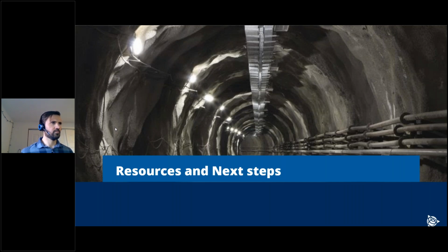Just came in. Oftentimes we lose GNSS connection inside a tunnel. Do inspection scans need to be shot from the exact same location for accurate results? Hey, Dane, thanks for the question. So this is where I think the real power of the SX12 is, because when you scan with the SX12, it will reference to your survey control.